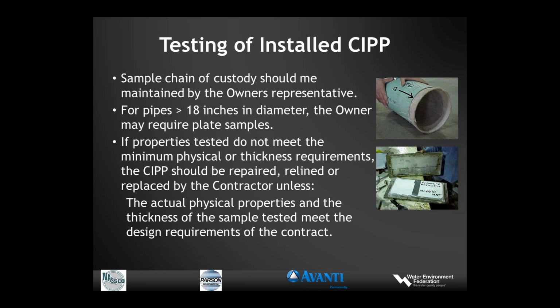If the physical properties tested do not meet the minimum physical or thickness requirements, the CIPP should be repaired, relined, or replaced unless the actual physical properties and the thickness of the sample tested meet the design requirements of the contract.